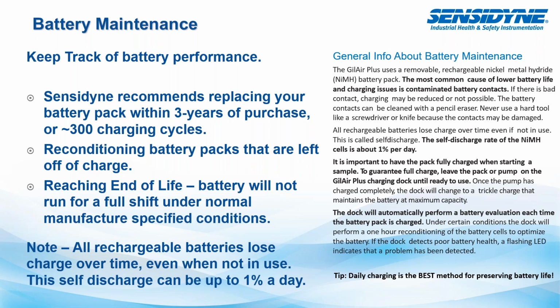usable format. And with the nickel metal hydride batteries, particularly, what you can do is put it on charge, let it charge up fully, then take it off of charge, let it run, put some back pressure on it if you can, so it actually runs that motor a little bit harder, depletes the energy in the pack, and then put it back on charge, let it charge up fully, and then do that again. If you can do that for 3 times, it will actually bring back that battery life as a mode to get the most performance out of that pack moving forward.